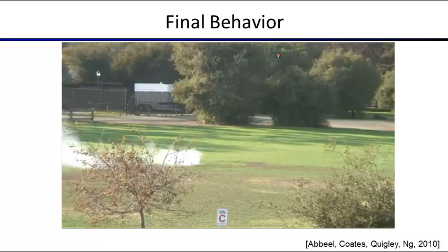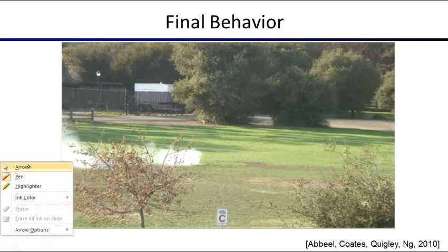Okay, so you do this, you have your trajectory, you now run the same algorithm that you can run for the inverted hover. Every 1/20th of a second, you recompute a sequence of actions for the next 2 seconds. That means 4 actions per time slice. 2 seconds means 40 time slices, so you have 40 times 4, 160 actions that you're optimizing over. And let's see what happens when you do that in real time.